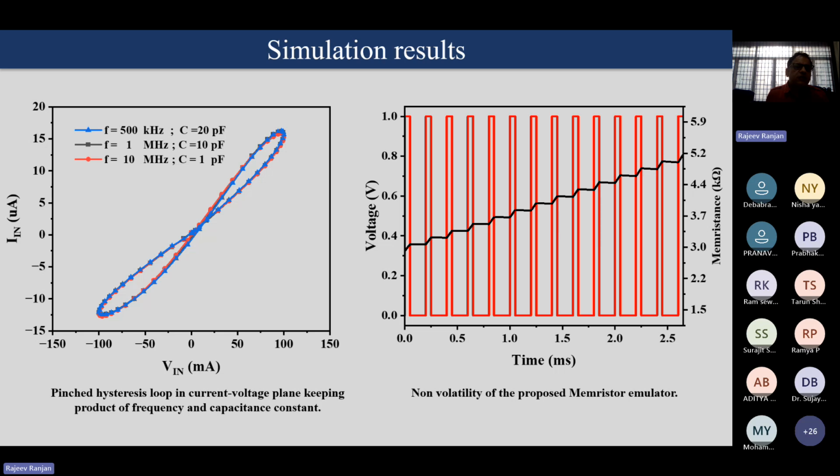Now the pinched hysteresis loop with constant frequency and capacitance, so all overlap one another. And this is the non-volatile behavior of the proposed Memristor emulator we have designed. You can see these are the spikes we are applying, but during the non-spiking period, it retains the value.